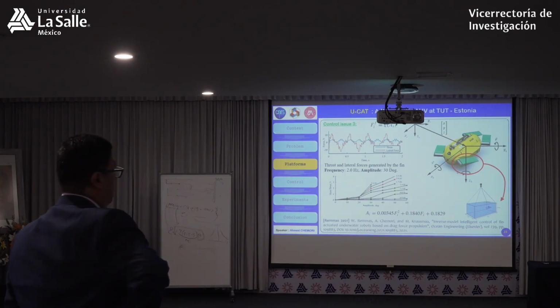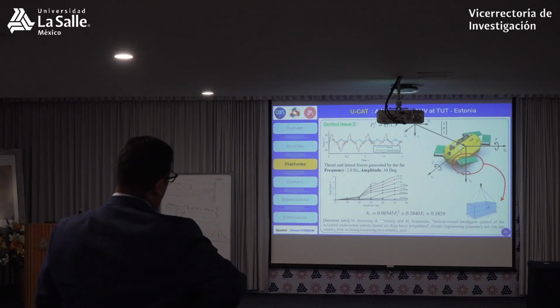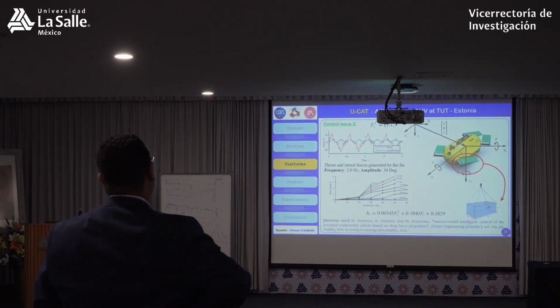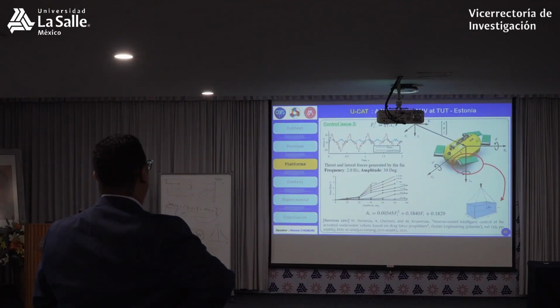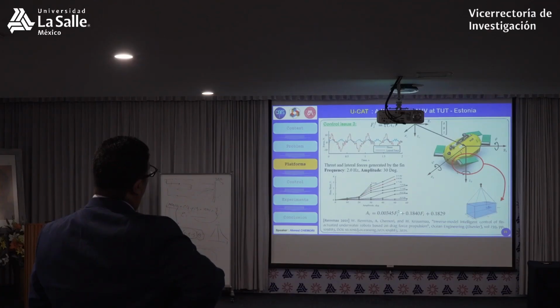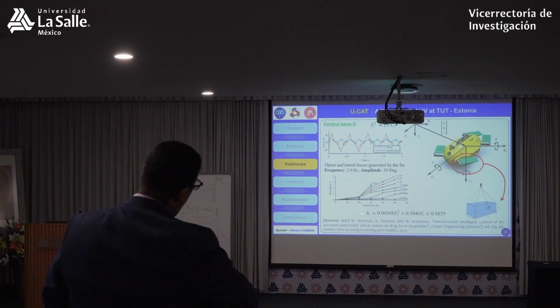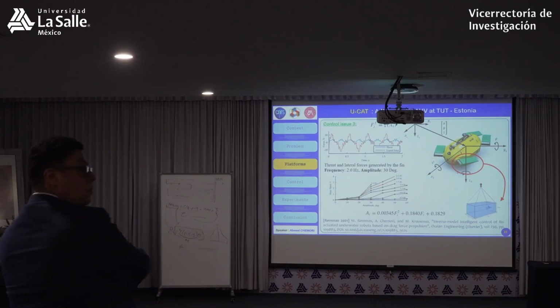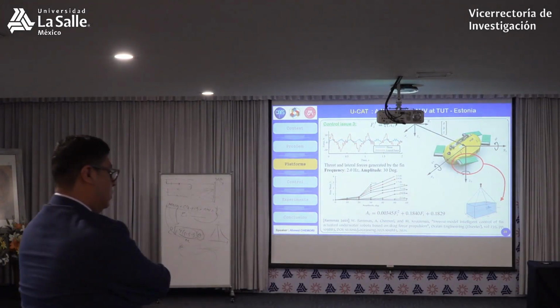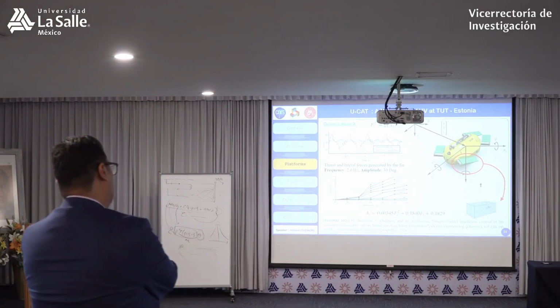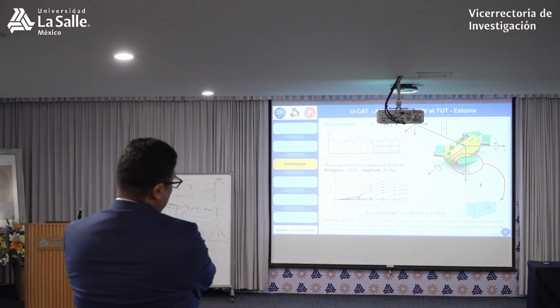Based on this approximation, we find this model, and another model which is written like that. Since we are looking for the amplitude to get a specific thrust, say I want thrust 10, we have to invert this model, and we obtain this simplified model. You put here the values of the desired thrust, F and F squared, replace them in this equation, and you obtain the amplitude that will give you that thrust. For sure, it's not so precise. However, we rely on the robustness of the control behind to compensate for the errors.